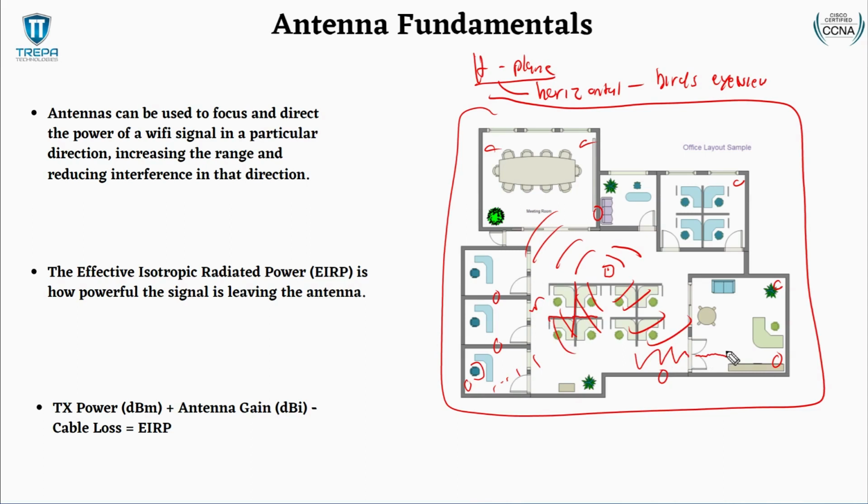With the H-plane, you don't always get that full view. You just get that horizontal view. So if there are access points on the ceiling, you may see that their signal does reach over here, but does it actually reach that desktop that may be sitting below this desk? That's where the E-plane comes in. The E-plane looks at that signal in an almost vertical view instead of horizontal. So let's say this is your desk and this is the desktop down here. Here's your little monitor. In the E-plane, we look at the signal this way, and how it comes in here, kind of looking at it from a side profile, whereas horizontal is that bird's eye view. So that's the difference between the H-plane and the E-plane.